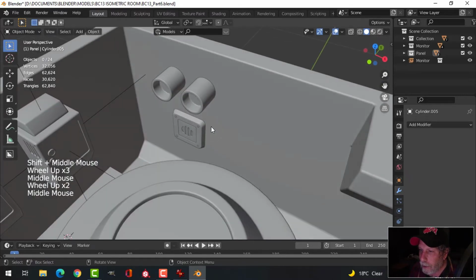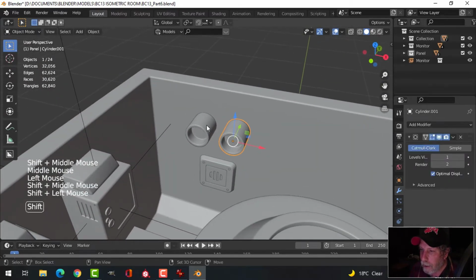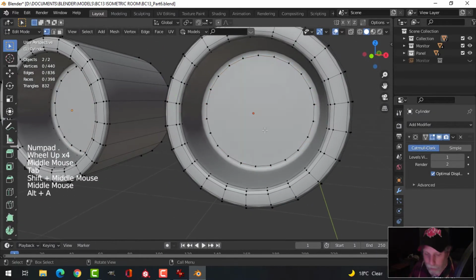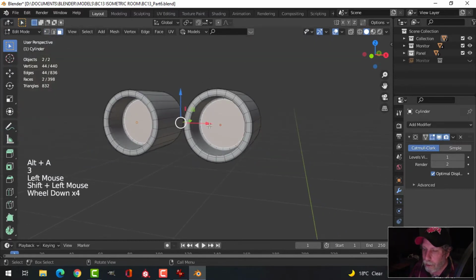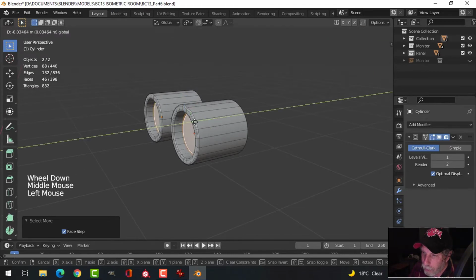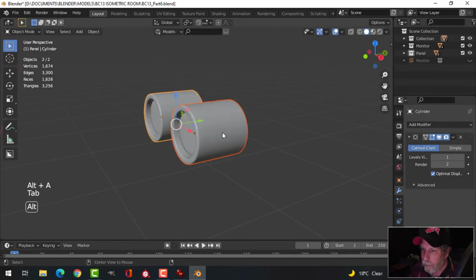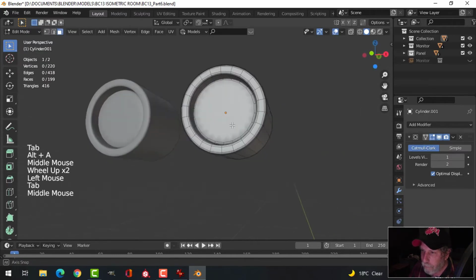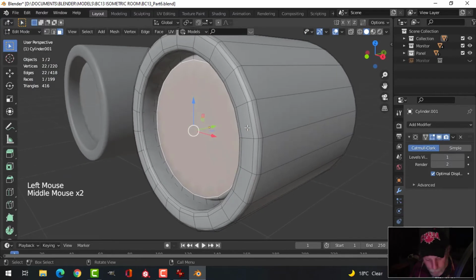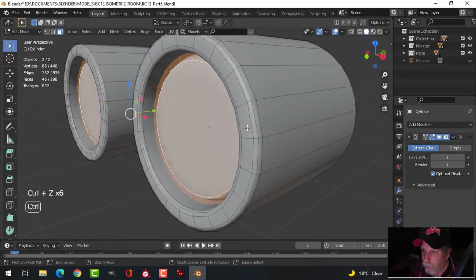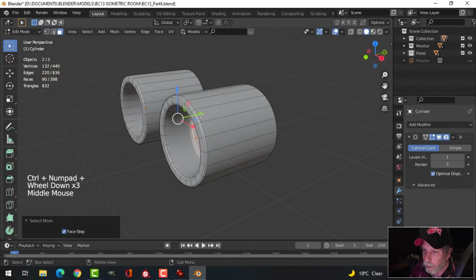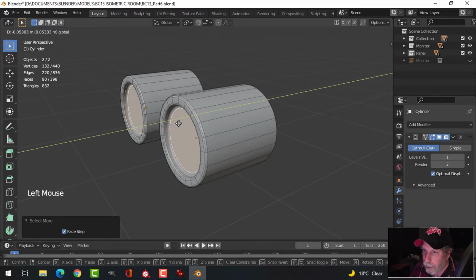And I think actually in looking at these, let's Shift H and just focus on them, press the period key to zoom in. I think I'm going to make a change here. I think I'm going to select, let's select both of them with Control plus to expand our selection, and I think I'm just going to pull this piece out to about there. Actually, maybe I am going to, let's delete, let's reverse that. I might come out Control plus one more. I think I came out enough. Let's do that.